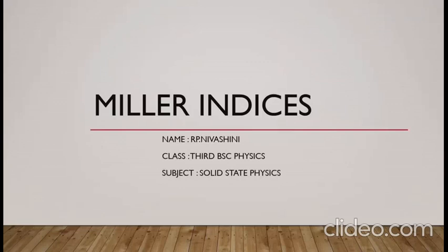In this video, we are going to see about Miller indices and its importance. Miller indices form a notation system in crystallography for lattice planes in crystal lattice. Miller indices are used to specify direction and planes. In particular, a family of lattice planes of a given Bravais lattice is determined by three integers h, k and l. Now, let's see the important features of Miller indices.